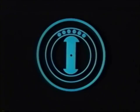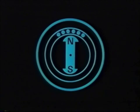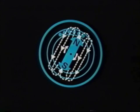But now, three-phase power is quite different and somewhat more difficult to understand. In order to understand a three-phase alternator, we'll again go back to the single phase for a moment. The field of an alternator has a north and south pole. As the field rotates, the lines of flux move through the armature winding and produce a current.